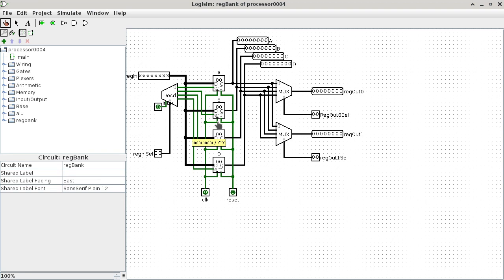But you can see how the input of register C, just like the input of all of the other registers, connects to reg in, the register input. So whatever I present to the register input is going to the input of all four registers at the same time. So do you remember what is the job of the EN pin of a D flip-flop?